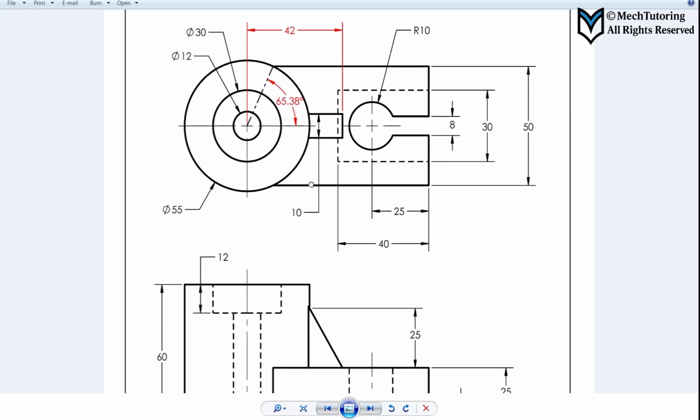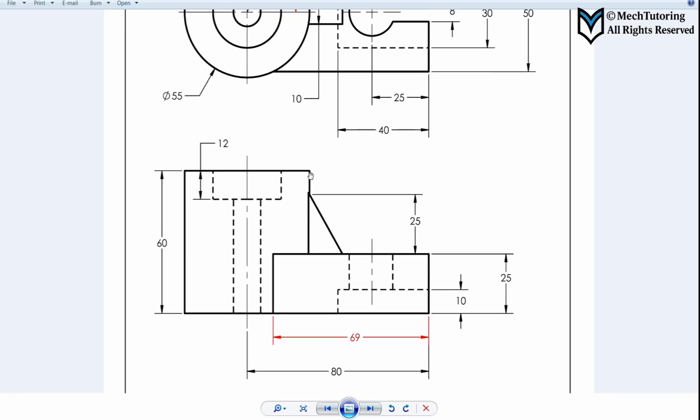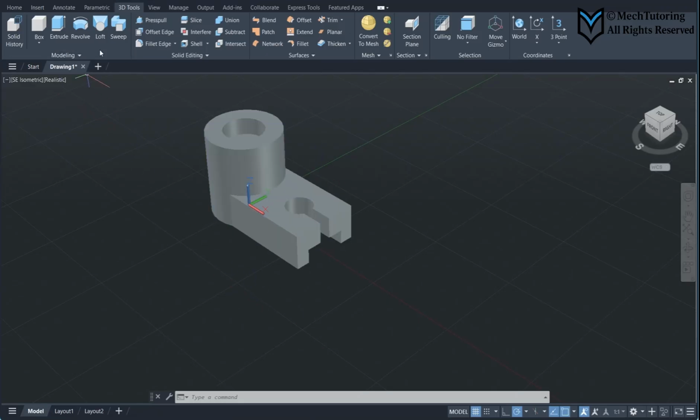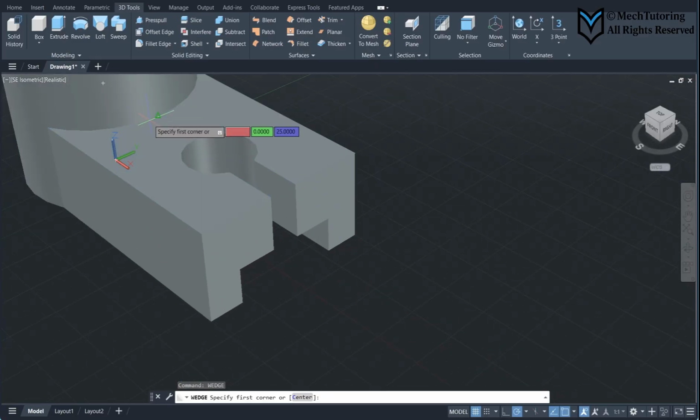So to create this wedge, we have to know how much is the length of it from this point until this, which is 14.5, because 42 minus 27.5 is going to give you that, okay? It's 14.5. So it's possible to create the wedge directly on this face. You can type in wedge here, but for that you need the starting point of the wedge, which is somewhere on the right of this, okay? First you have to create an edge on that, on this surface.